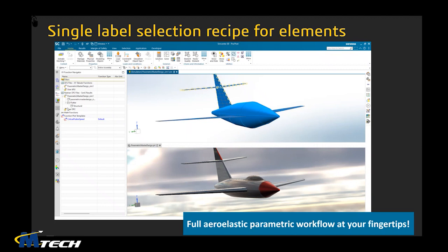This update has been building over the course of several previous version releases, and it seems as though Siemens has really begun to smooth out the workflow for aeroelastic analysis. Previously, it was not even possible to set up an aerodynamic configuration investigation with flutter, static, or dynamic solutions without using external scripts. With this release, users now have a fully integrated parametric workflow for aerodynamic and structural models, as well as for the whole aeroelastic analysis setup.